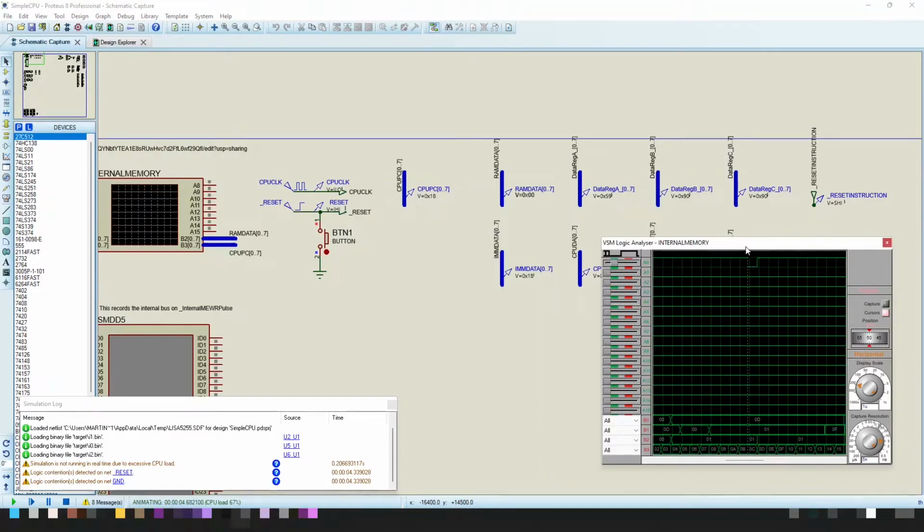And as if by magic, the capture light has gone off, indicating that the trigger condition has been met. And we can see here that a trigger condition has been met and accepted and actually logged in the logic analyzer. If I zoom out, you can see that there's a memory write here, there's a memory write there. I can scroll along here, and I can see that there are several memory writes, as you would normally expect.